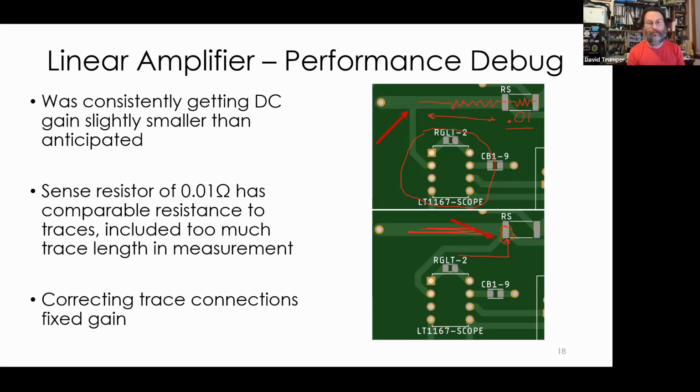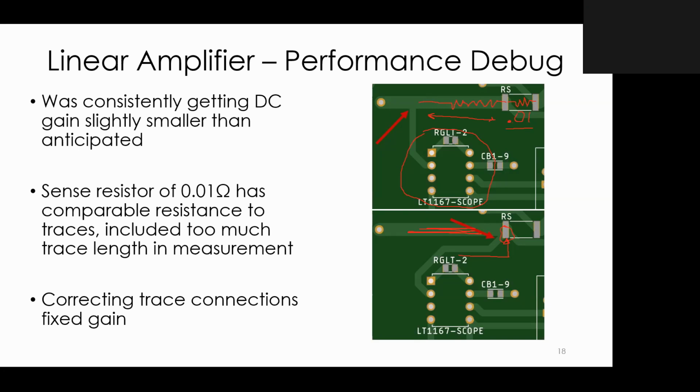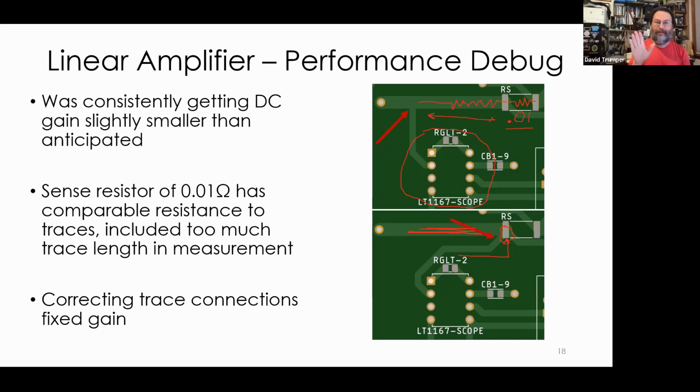We wouldn't know the calibration, but yes, if you wanted to minimize cost, the problem would be you would be very sensitive to the thickness of plating. And also, if you buy an accurate resistor, they're specified, they make them with an alloy that has a low temperature coefficient, because don't forget the resistance of metals changes with temperature. So if you're trying to do accuracy, I would not do a PC board resistor. Plating thickness varies easily by tens of percent. You're not going to be calibrated. And then the temperature coefficient of your resistive material might be much worse than one you buy that's specified. Good question, though.